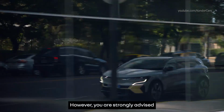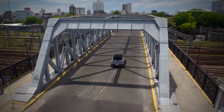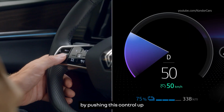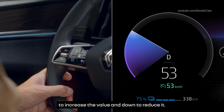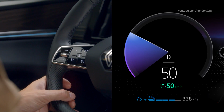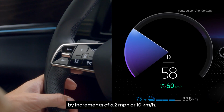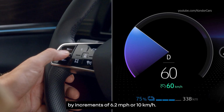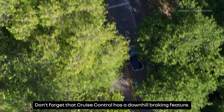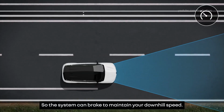However, you are strongly advised to keep your feet close to the pedals to be ready to intervene if necessary. You can change the cruise speed at any time by pushing this control up to increase the value and down to reduce it. Press and hold up or down to change the speed by increments of 6.2 miles per hour or 10 kilometers per hour. Don't forget that cruise control has a downhill braking feature, so the system can brake to maintain your downhill speed.